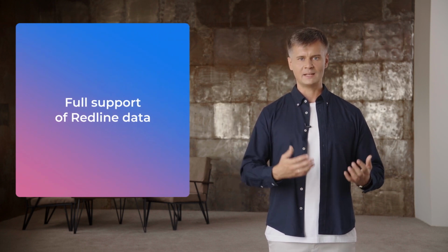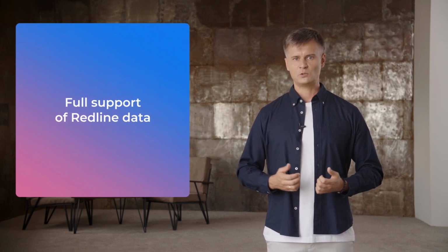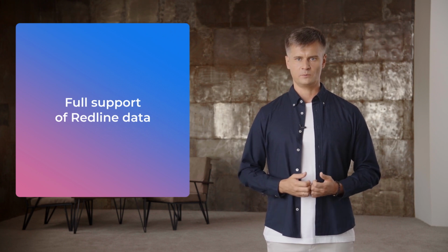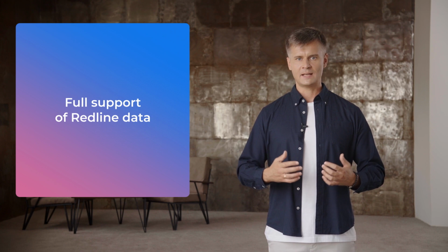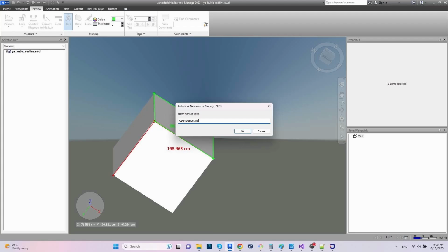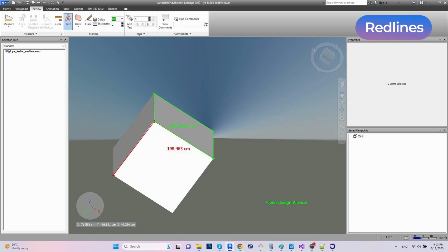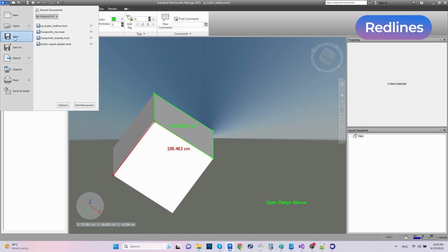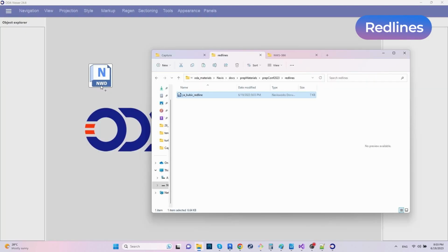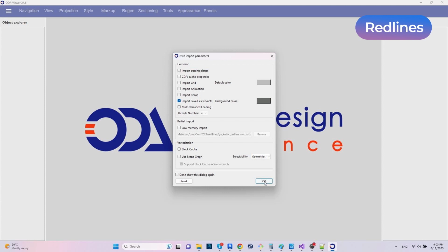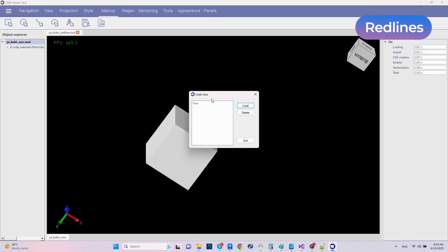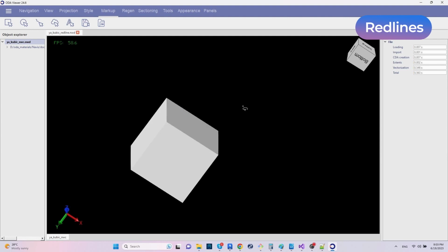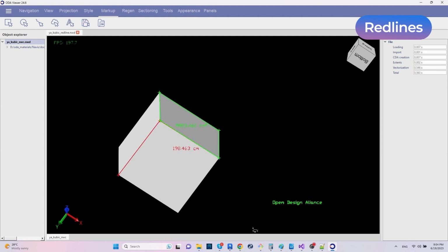Navisworks files allow appending different red line types to the saved viewpoints for the model review. BimNV SDK supports all types of redline data in models. Users can open a Navisworks file with redlines in ODE Viewer and select Import Saved Viewpoints property in the Import dialog. When the file loads, users will be able to choose the markup menu and select viewpoints with needed redlines.